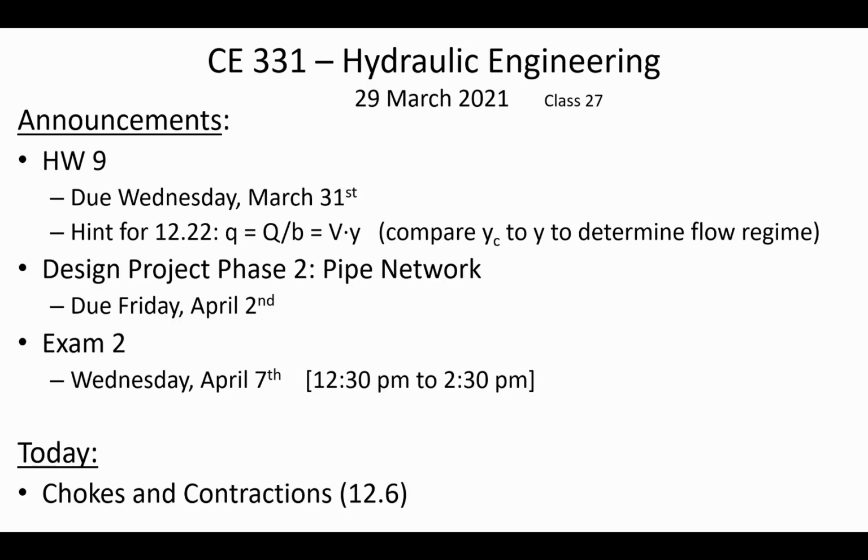All right. So I sent you an email earlier this morning with a tip on homework 9, which is due on Wednesday. And what I wanted to let you know about that problem is that there's another way to solve for flow per unit width. And you might have already derived this yourself, but remember, flow per unit width, lowercase q, means the flow rate, large Q, divided by the channel width B.